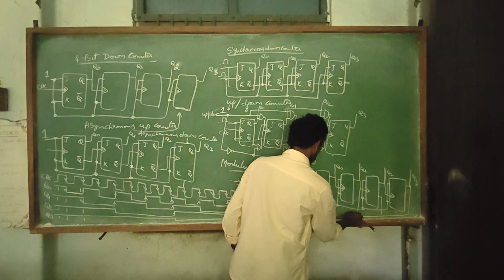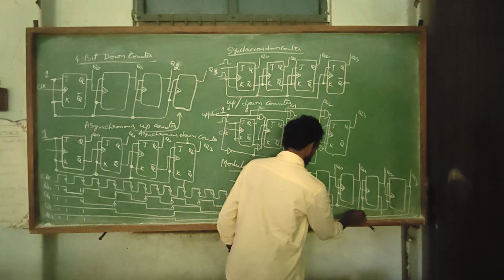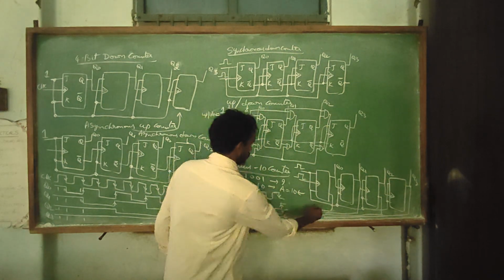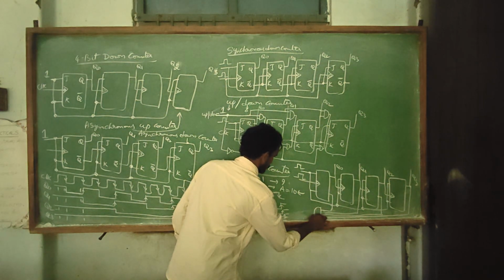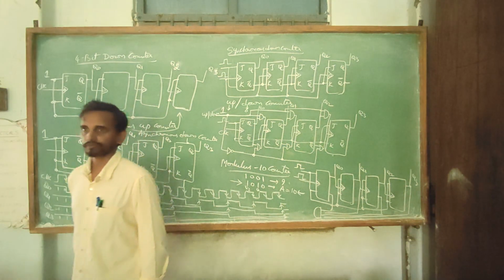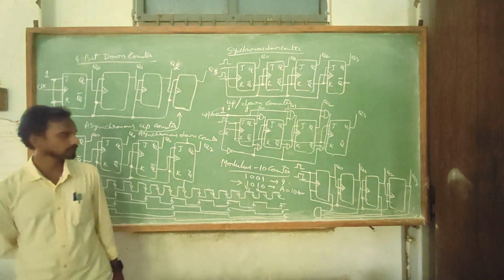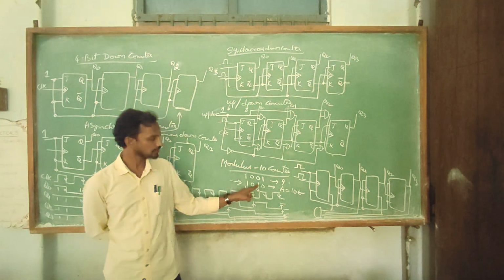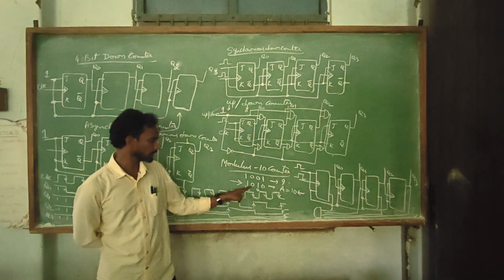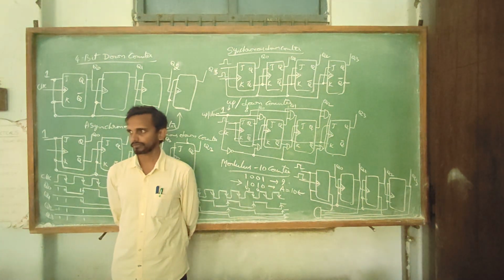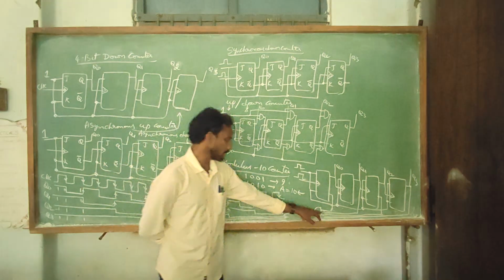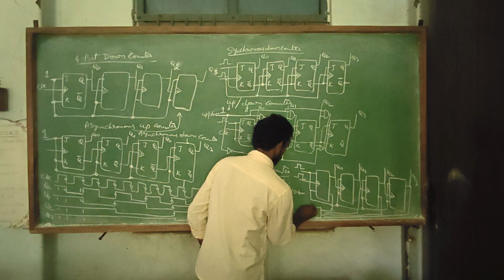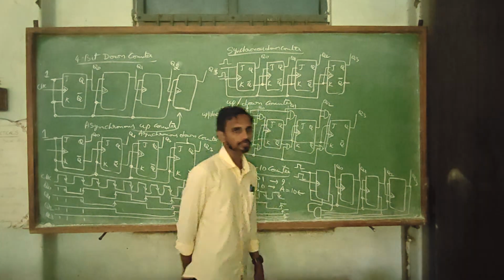I am collecting all the 4 conditions and giving them to an AND gate. Q0 bar, Q1, Q2 bar and Q3. So when all are 1, the output of the AND gate will be 1 and I will give that output to the reset button.